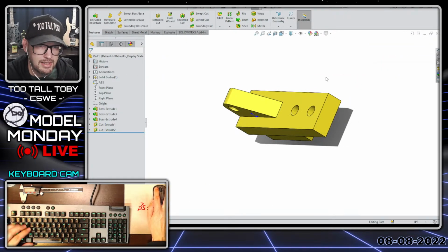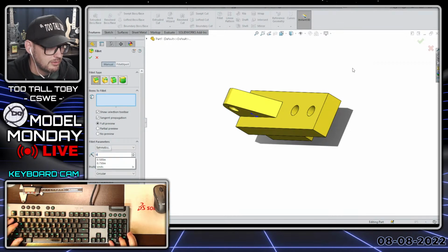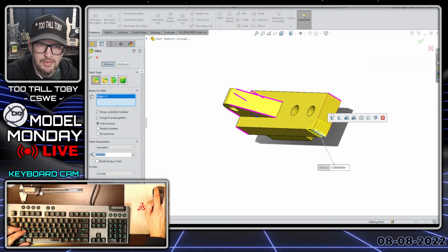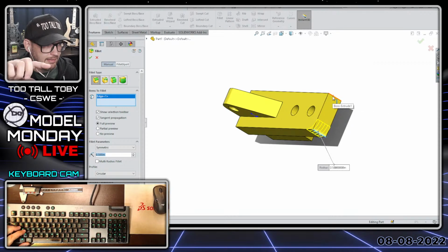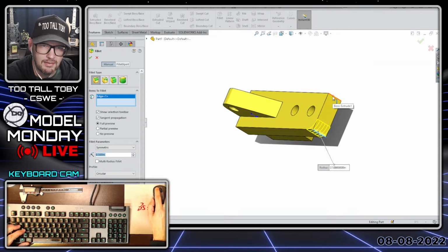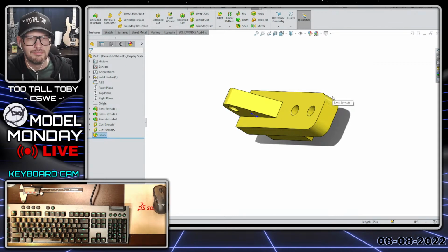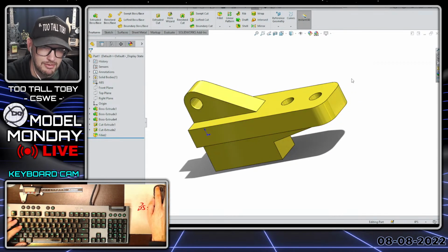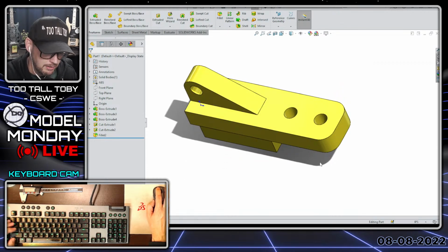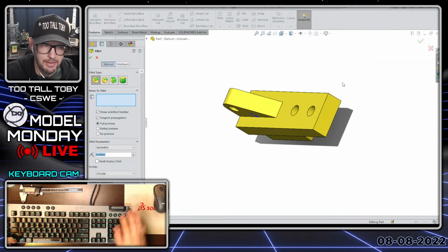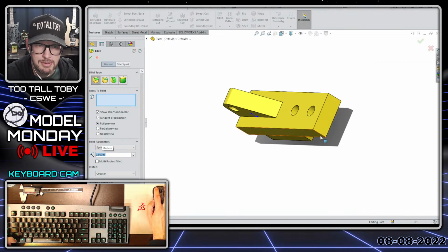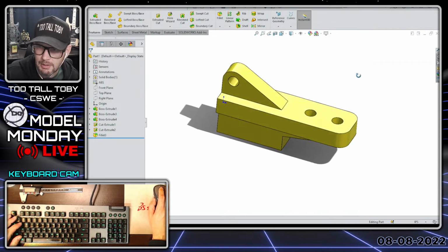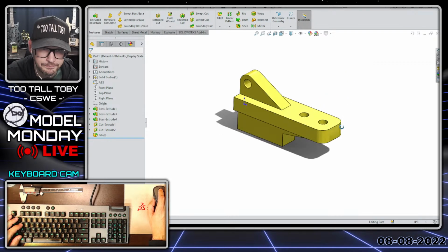So that means that as soon as you get into the command S key fillet, you can immediately type 0.5, the radius. And then you can pick the first edge and then move your mouse. And then this is like left mouse button, right mouse button. So you like left, right, done. So it's another really good move to learn when you're trying to learn these common commands that we use all the time in SolidWorks. Like how can we quickly get through creating a fillet? Well, if you just learn that workflow, S key, fillet, immediately type in the radius, pick the first edge, pick the second edge, pick the third edge, pick the last edge, and then immediately right click. That really can help you speed through that process of adding those fillets.